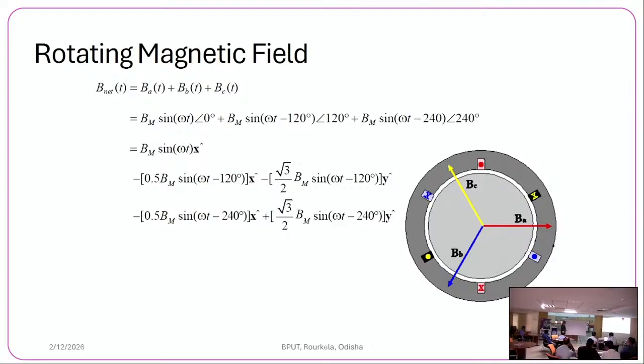Okay. So this is 60 degrees. The component of FB on the horizontal axis is FM by 2 into cos 60 degrees. Cos 60 is 1 by 2. This is also 1 by 2. So total will be FM by 2.